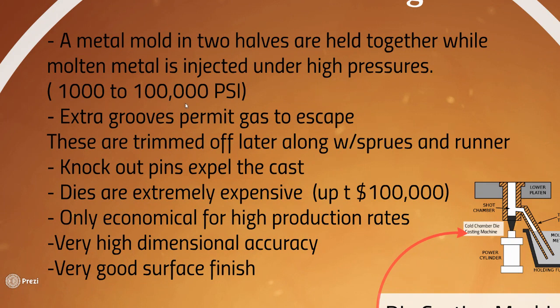So other characteristics are you have grooves in them to permit the gas to escape, because of course that is very important. And these gateways to the actual mold cavity, they're trimmed off later on, along with the sprues and also the runner and gating system.